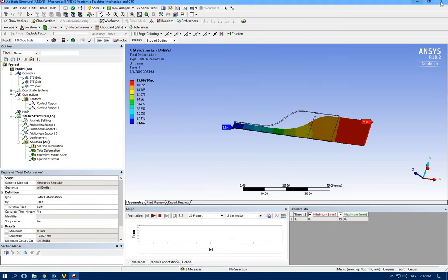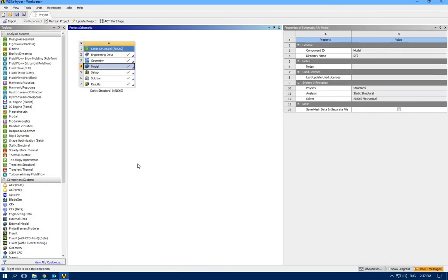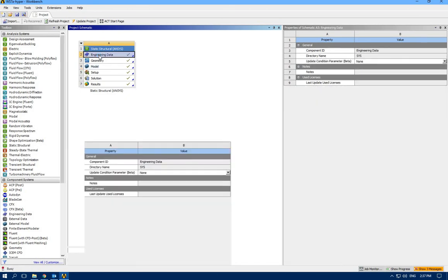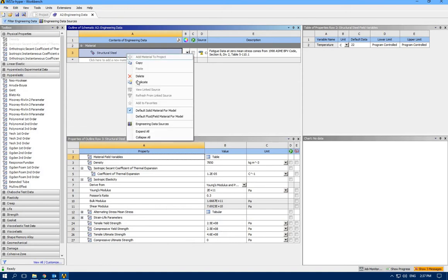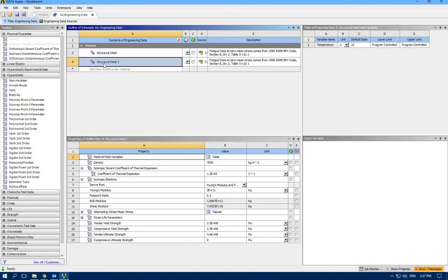Now let's close this, because we already know these things, and I'm more interested in hyperelastic materials. To generate a new material, I can start from the beginning, or I would like to duplicate this one. Name it, for example, elastomer.